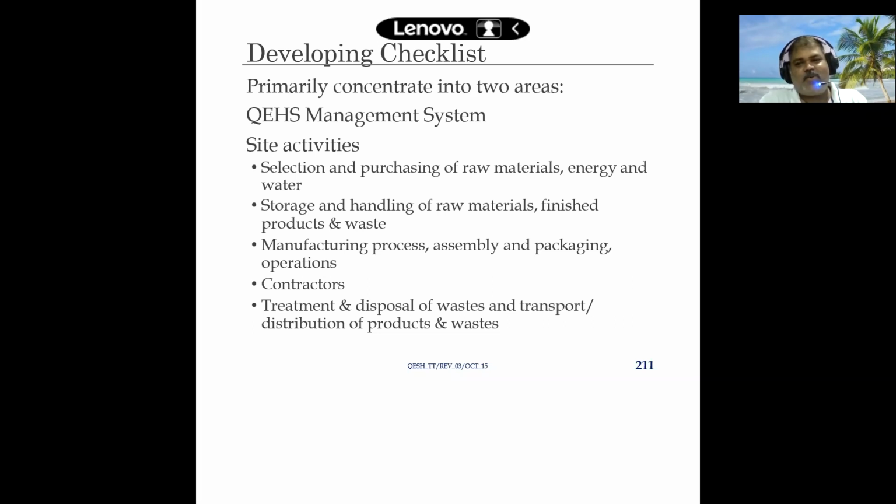If the CONQUAS score you put at 80 to 90, then your standard for quality is there. Then if you break down the details, maybe you go for wastage, how many percent. Then for safety, it's basically ASR and AFR, your accident severity and frequency rates.